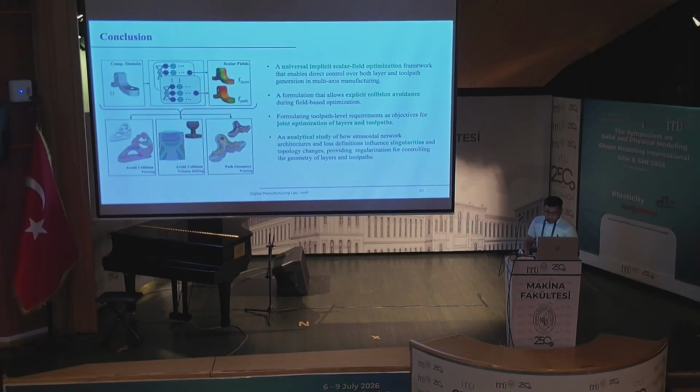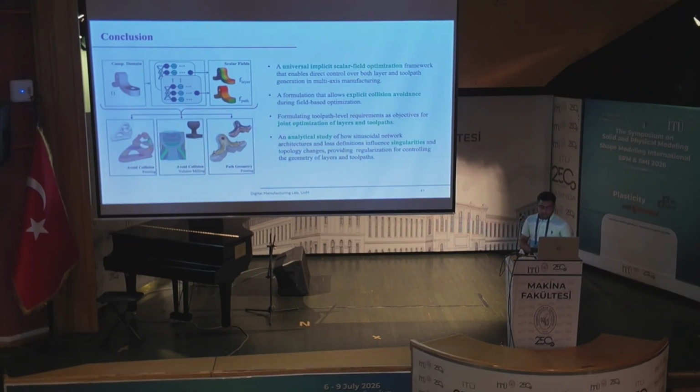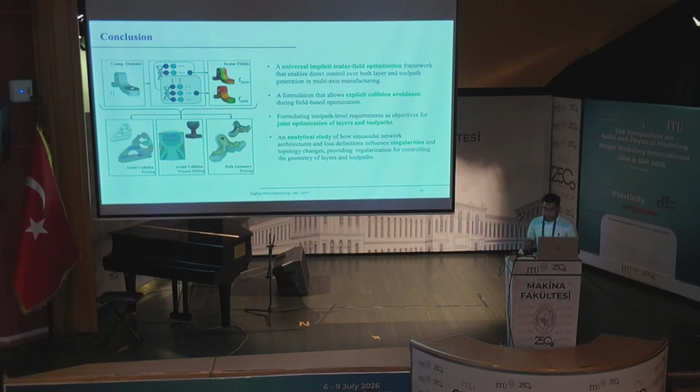As a conclusion, we generated a universal implicit scalar field optimization framework that enables direct control for both layer and toolpath generation in different multi-axis manufacturing applications. We also formulated an explicit collision avoidance for field-based optimization, and showed how different loss functions can be used for joint optimization between layers and toolpath, and clearly this has several benefits. One of them I showed.